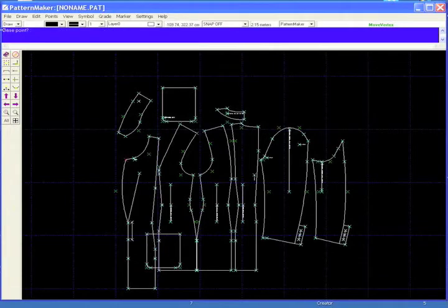The next question is base point. From which point do I want to move the point? I want to move the point from the point itself, so I click on the point. And now when I move the mouse, you see that the color is changing. You can make it as long as you want or as short as you want. And you can also type in distances. When you want it, for instance, 3 centimeters wider, you type it in on the keyboard.